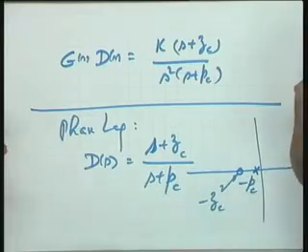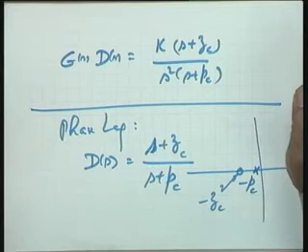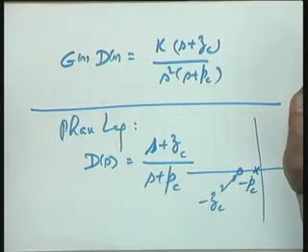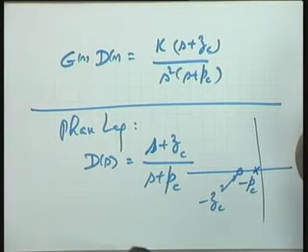In that particular case you can think of adding the phase lag compensator to improve the steady state accuracy, because you will be able to control Zc and Pc suitably so that the transient performance of the uncompensated system is not deteriorated.